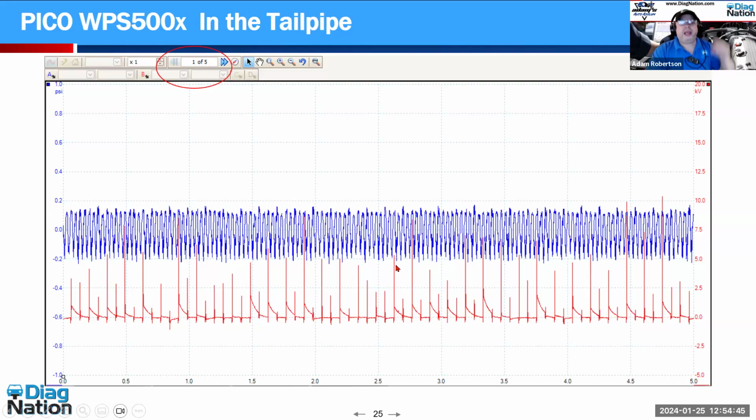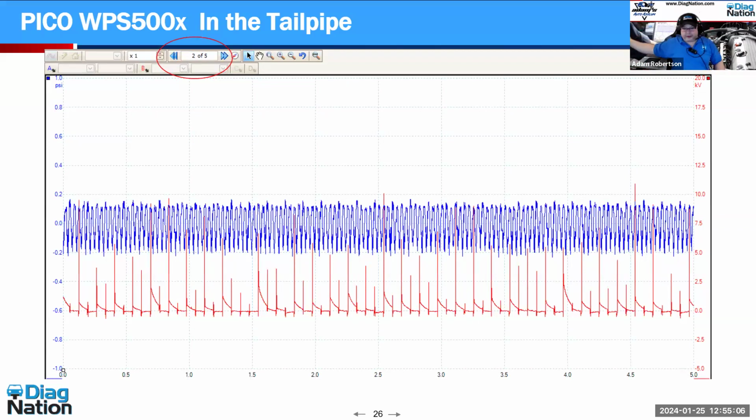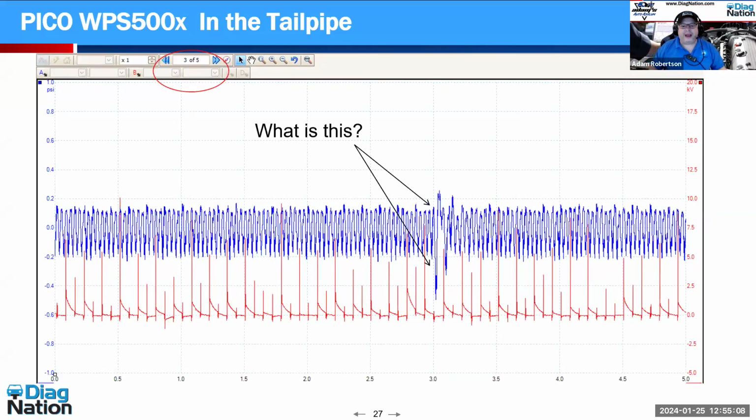So what you see in the exhaust pulses of this car is from here to here, 720 degrees, or 4 firing events. 1, 2, 3, 4. And it's consistent. Out of those 5 seconds, I got nothing. And then it happened. You got to remember, guys, this is an intermittent problem. It's running perfect, perfect, perfect, perfect, perfect. Wow, something is amiss right there.